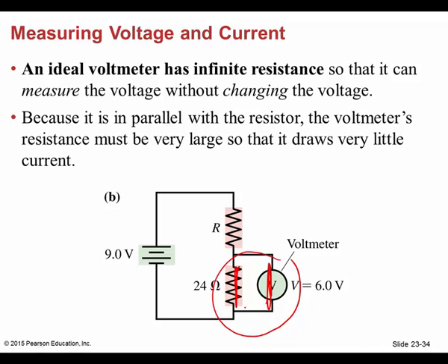And so whenever we check the voltage on resistors, no matter whether it's series or parallel, you always have to hook your voltmeter up parallel to the resistor. See how that's parallel? See how you touch it here and here? It's not in series.